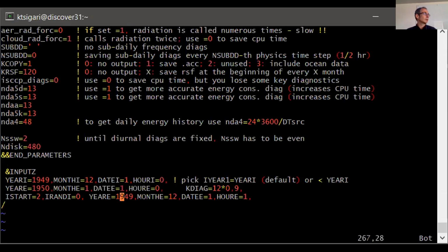When you use a supercomputer, there are limitations on how much wall time you can use per simulation. That's why we need restart files. In our case, depending on which queue you go in, we can run for 12 or 24 hours, and then we must stop the model. Otherwise, it will just crash. The computer will kill it. So if you have no limitations, who cares about running a setup hour? You can do everything as a fake setup hour. But it can be weird if you have to stop the model.